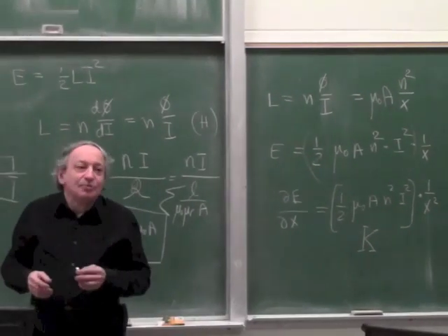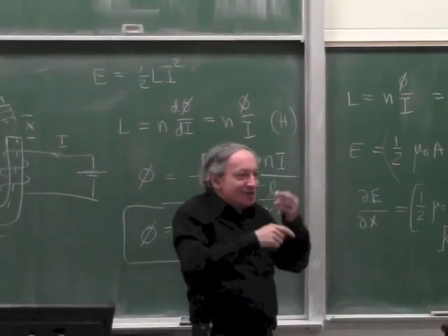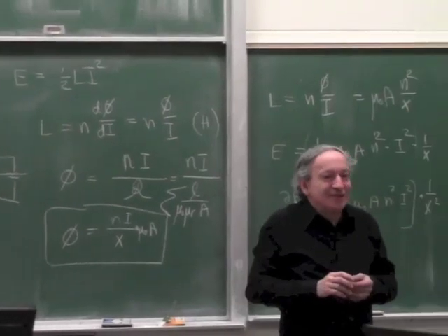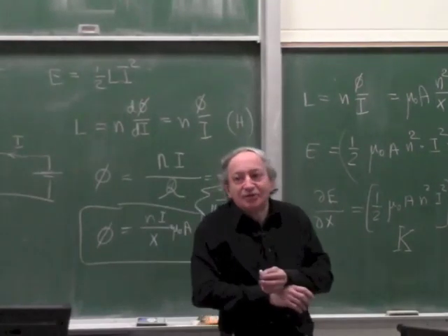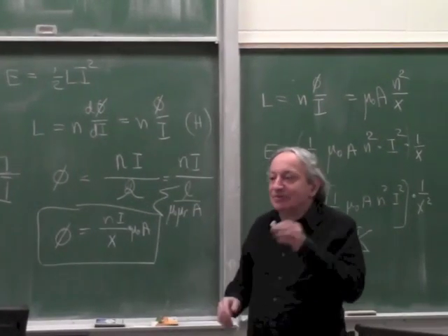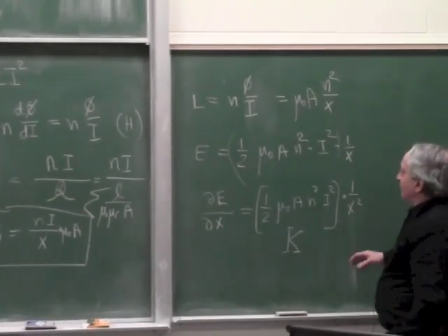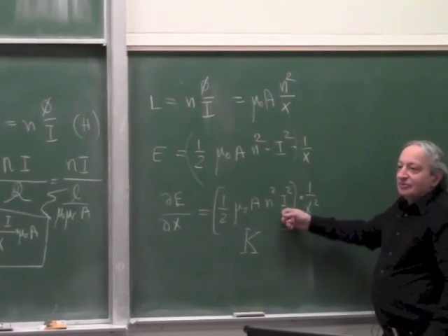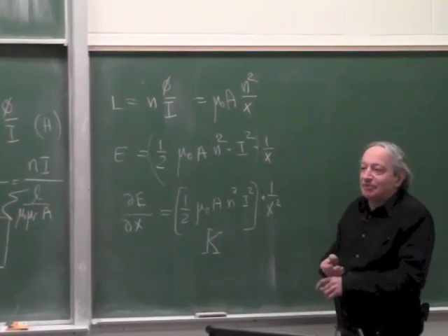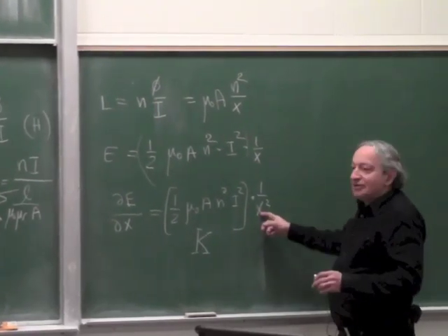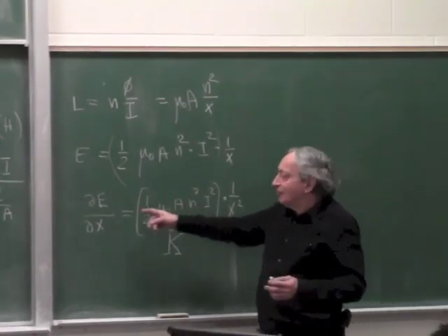Now you can say today with computers you can measure x and then change the gain, because the computer can look at x and change the gain of the servo. Basically you have a variable gain amplifier and you make the whole system behave like constant gain. But there are problems with that too, which I won't get into right now. Okay, so these systems are nonlinear with control current. Both things are actually bad, because both mean variable gain. Gain depends on position, and gain depends on the drive current. Because if you double the drive current, the force goes up 4 times.